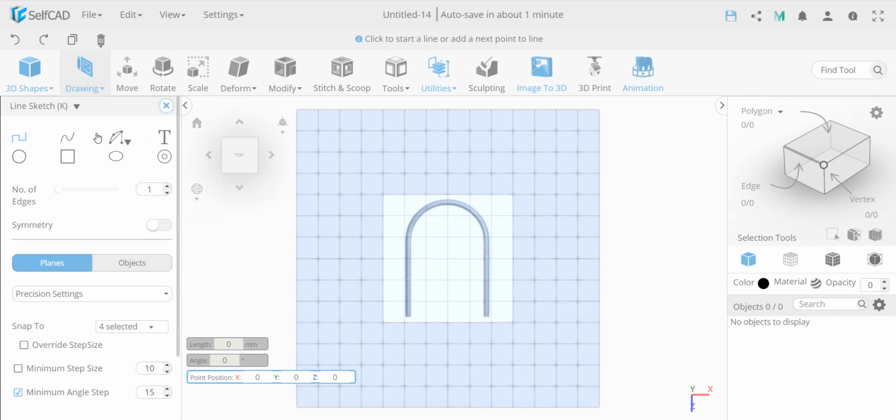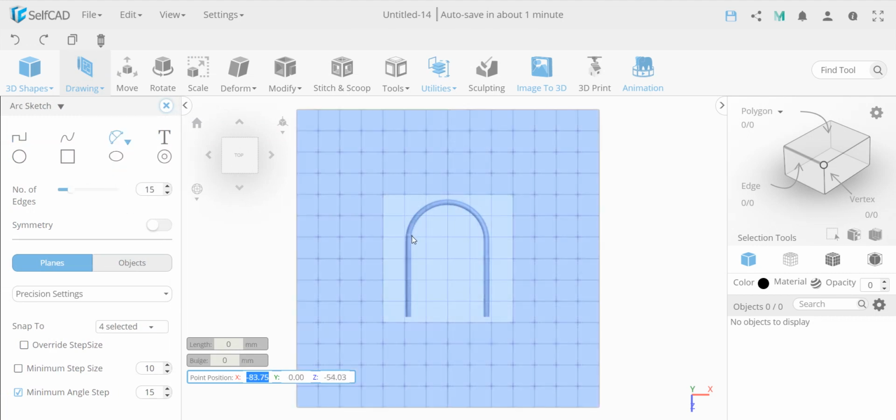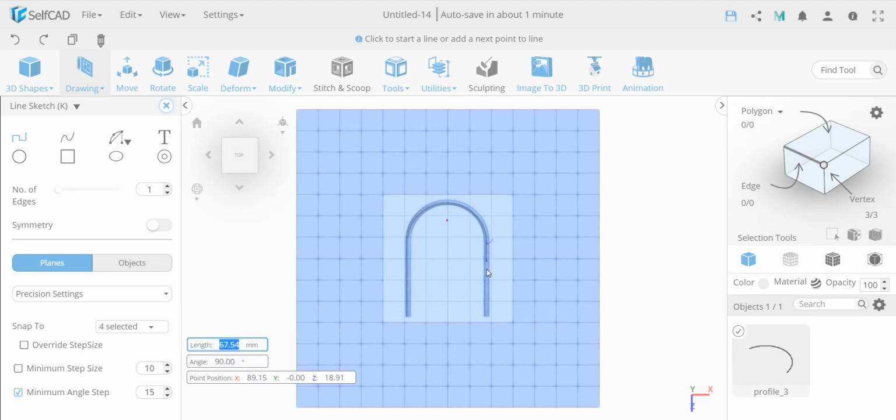And I'm going to start drawing a sketch where I'll start with the top, the circular movement. I'll take an arc and move it from this point to this point, and I simply create this part arc over here. Now I'm going to go back to the line drawing, and I try to snap to this line over here, and I draw this part, and I press escape to stop the line, and then I draw over here and escape to finish this one.